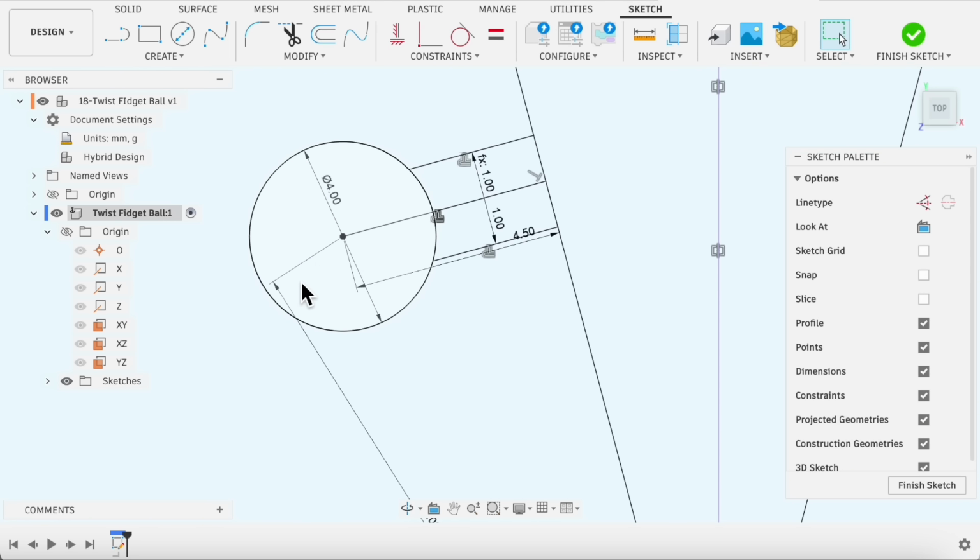It'll slide freely inside the matching groove on the adjacent slice. Think of this as a modified dovetail joint. The wider head prevents pull-out, locking radial movement while allowing vertical sliding. Let's select this center line and press X to turn it into a construction line. Okay, the interlocking sliding mechanism is ready.